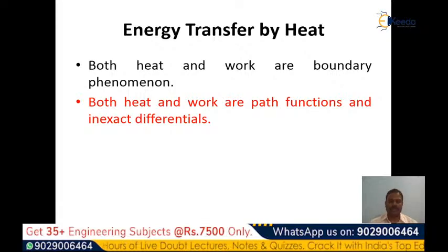The magnitude of work involved depends on the path that is followed, as the area under the curve is the measure of the work involved in change of state from initial to final. So it completely depends on the path that is traversed.